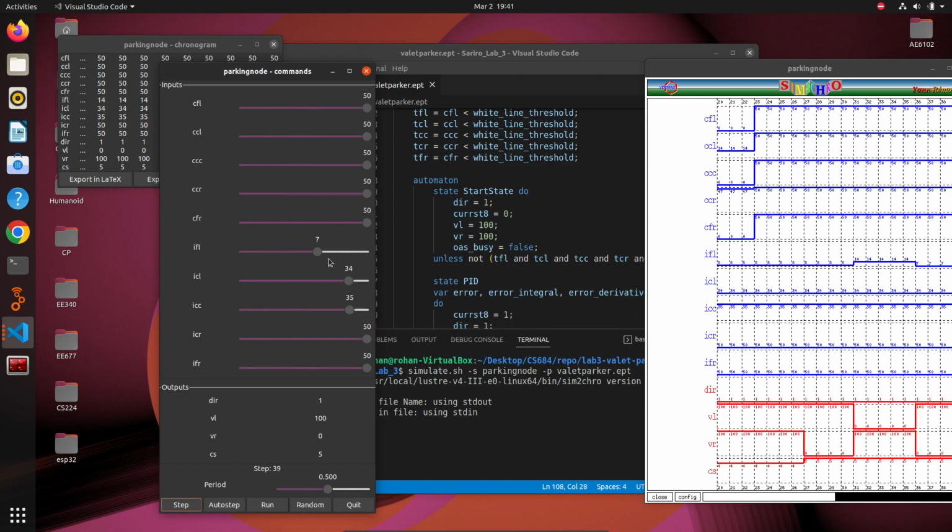This will keep happening until we reach back the white line. So this will make it move around the object by maintaining the distance, and when it reaches back the main line, then this CC sensor value will go less than 10. Then it should go into the next state, which is state 6. In state 6, we will slightly move forward because the white line sensors will be in front of the circular thing, right? So we go forward, it will make sure that it goes offline, and then after that we will turn right, so that after turning right 90 degrees, the white line sensor will come in front of the white line.